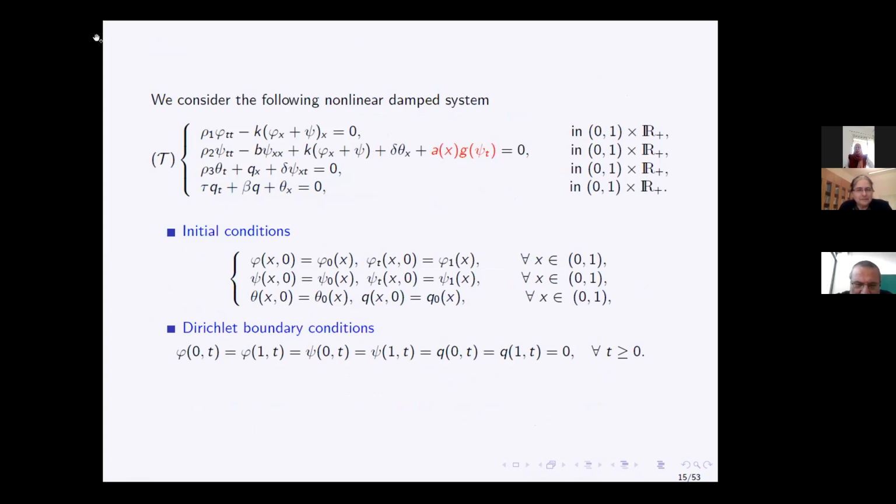So normally in thermoelasticity, it is assumed that the mechanical dissipation is transformed completely into heat, and that the full energy is conserved. But here it seems that you neglect the contribution of the mechanical dissipation to the energy balance. And so it seems that your energy is decaying to something, possibly to 0. So the temperature is decreasing in principle in your process. So what is happening with the dissipated energy in reality in your model?